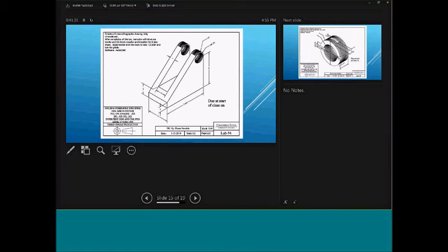This one just has some hidden line challenges, the way that hole goes through those rounded tops and where the lines become tangent to the circular geometry and the oblique surface, and have that channel running through the front of it. It gives them some challenges on some of the orthographic views and makes them think about how to transfer their lines from one view to another. If they're just drawing the views independently and deciding where these lines should be individually, they usually get it wrong, whereas if they would transfer things from view to view, they would have a much better drawing, and they start to understand that here in this lab.